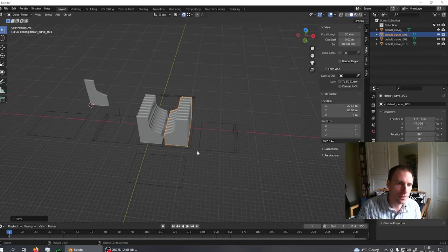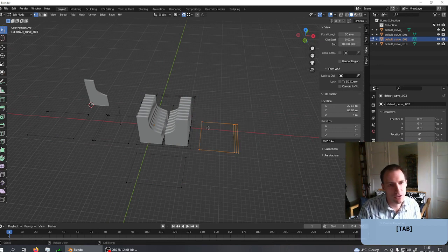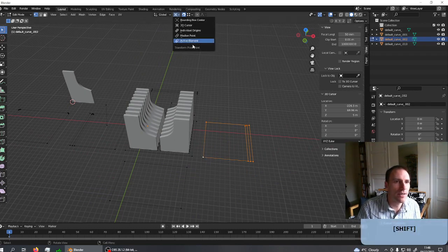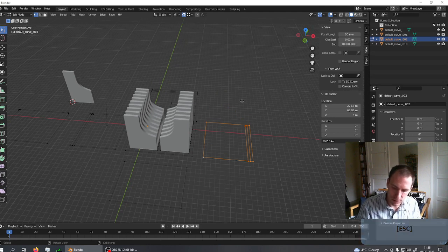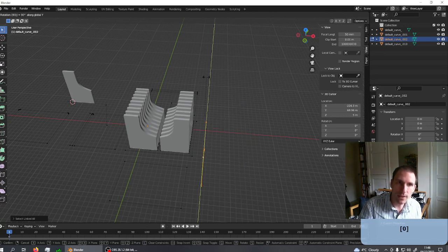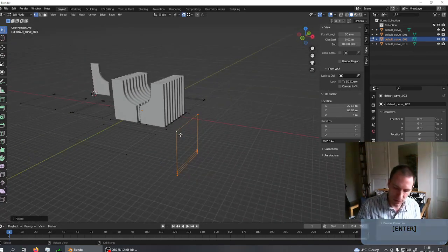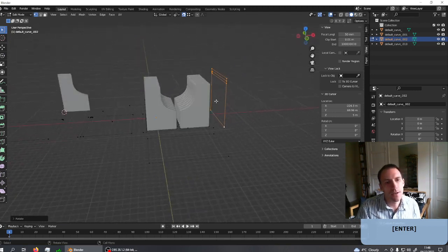There's a couple of ways we can do this. I can now grab this mesh, go into edit mode, and I can start creating the shapes. If I go for rotation and we go for active element, there we go. So we can go RY, and bring it up. Oops, I missed a bit. If we go for Control L for everything linked, RY, and then we want to go 90 degrees, maybe 180 from that, RY 180, and there we are.